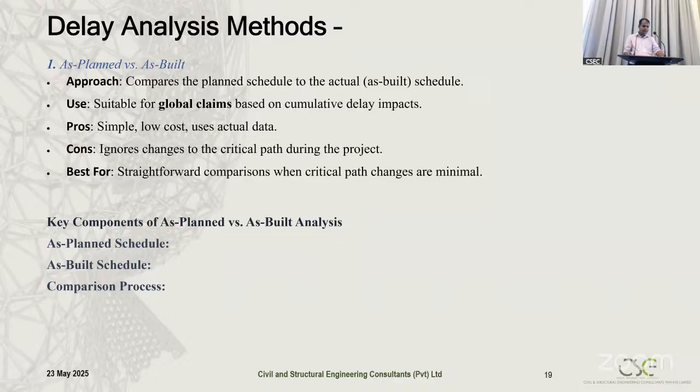Okay, in this method, the key components are the as planned schedule. For this method only I will explain these terms. For the next methods, I am not going to explain because we have limited time, so you can remember. The as planned schedule is the baseline schedule that is developed at the start of the project. It outlines the sequence of construction activities, their durations, start and finish dates, and their interdependence, which is relationships.